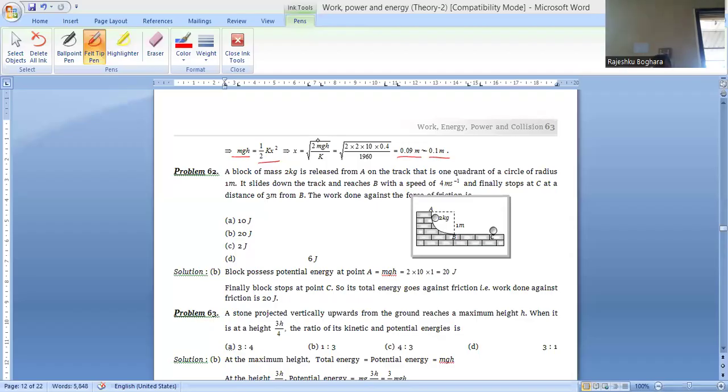This mgh, only 80% of that energy is obtained as output power. So here we write power equal to work done by time, mg delta h, where h is the height difference, 500 meter, 550 minus 50. m is given as 2000, g is given as 10, per second.